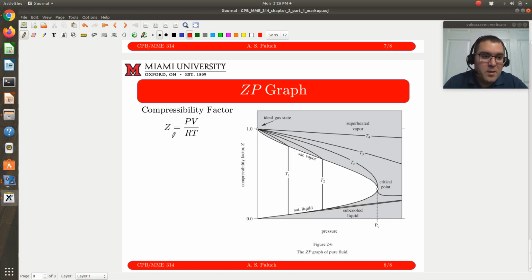So we'll enjoy working with Z later on when we work with cubic equations of state, or just in terms of numerically trying to model data altogether. To jump forward, the big advantage of working with Z is that Z is dimensionless. The value of Z typically varies between 0 and 1. So if I'm trying to model vapor and liquid in coexistence, it's nice having a quantity where my vapor value is going to be close to 1. My liquid will be much smaller but greater than 0.